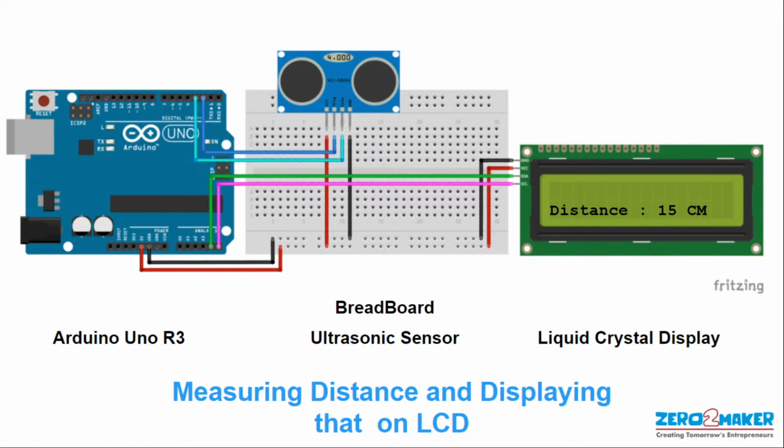So here we have used that particular ultrasonic sensor. We have pinned it up in a diagram, which you can say we have added onto a breadboard, and on that breadboard the wiring you can see has been connected to Arduino. So there are 2 pins going to Arduino, and there are other 2 pins which are supplying the power to the ultrasonic sensor. So this is how the sensor is getting powered, and it is sending the data to Arduino.